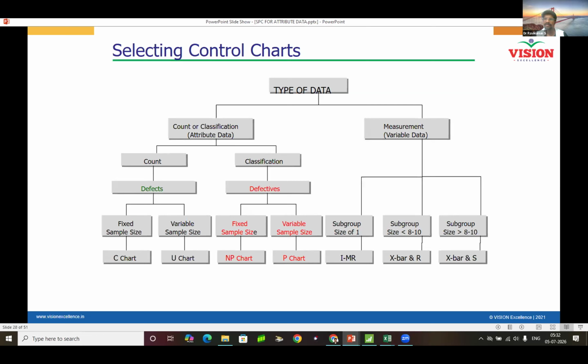For example, if the population is 100, choosing 10 is okay. If the population is 1,000, at least you must go for 50. Then only it will be a real representation of the population. Any thumb rule, sir? No, obviously there is no such rule. You have to choose as per your process. For process industries like chemical and textile, it might vary. Depending upon your QAP, you have to decide the sample size. If your QAP demands more stringent measures, you have to go for a higher number of samples. If your QAP is a bit lenient, you can go for fewer samples. So you have to decide.